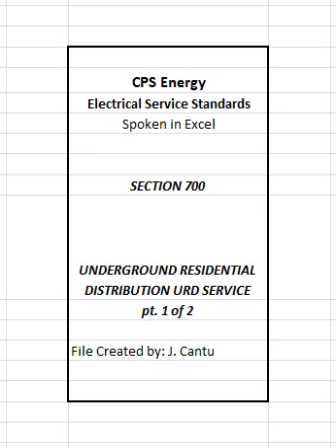1. No transformers, cable, or other CPS Energy facilities will be installed in rear or side lot locations unless the grade of the property is 10% or less and a drivable surface is installed to access transformers. All transformer pad sites are to be leveled by the developer. 2. No transformers, cable, or other CPS Energy facilities will be installed in areas that are prone to flooding. Any conduits installed across an earthen drain must be encased in 1500 psi concrete.